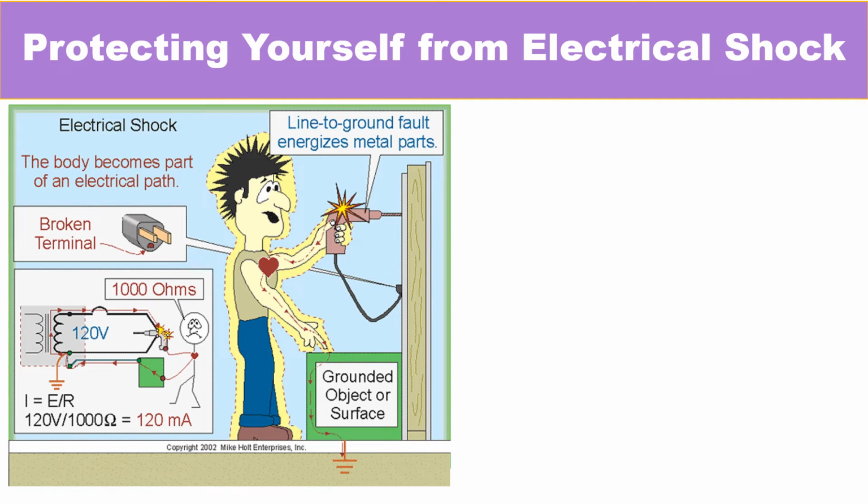Last time, I mentioned a little bit about electric shock and how it is important to avoid any type of electric cord damage that you see on the highway and so on, where the cord is droopy, or that when you're in the vehicle, you shouldn't come out, those kinds of things. But here's something that I want to point out to you. It's quite common, more than you think. I want you to look at the plug over here. Can you see one of the ends, I like to say terminal, at the bottom? This was intended for grounding. But the thing is, that part is missing.